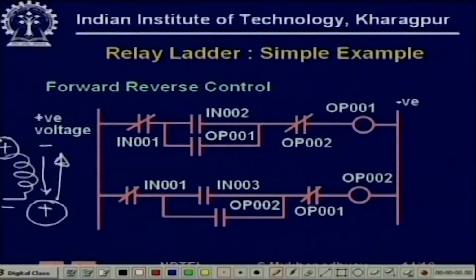Now a potentially hazardous situation exists, that is, if by chance they are two different switches and they are pressed together, then the positive terminal and the negative terminal will get shorted. This may cause an accident. So we do not feed the push buttons directly; rather, we take them through a PLC, so that we ensure that even if they are pressed together, no such problem will occur. So now we see what is going to happen.